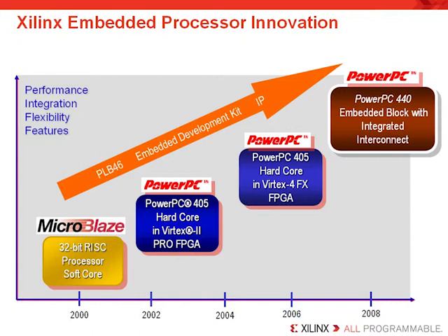Xilinx's embedded processor solutions include the MicroBlaze soft processor core as well as the PowerPC 440 hard processor core. Now, MicroBlaze is a soft processor core, which means that it is built with standard FPGA logic resources, including LUTs and registers, and it can target any of Xilinx's FPGAs. MicroBlaze is a 32-bit RISC processor that can obtain performance over 300 MHz, but this again will depend on the device family and speed grade as well as the embedded system that you choose to build.